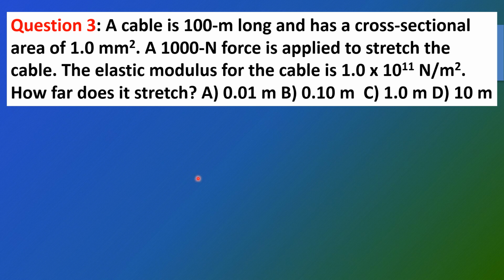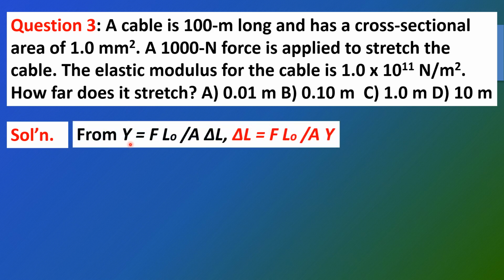So our solution to this question, using the formula for Young's elastic modulus, capital Y, is equal to F L naught divided by capital A multiplied by delta L, we are going to come up with a working equation in finding the change in length or elongation, delta L. Because the question says how far does the cable stretch, the question implies that we are going to determine the change in the length or elongation.